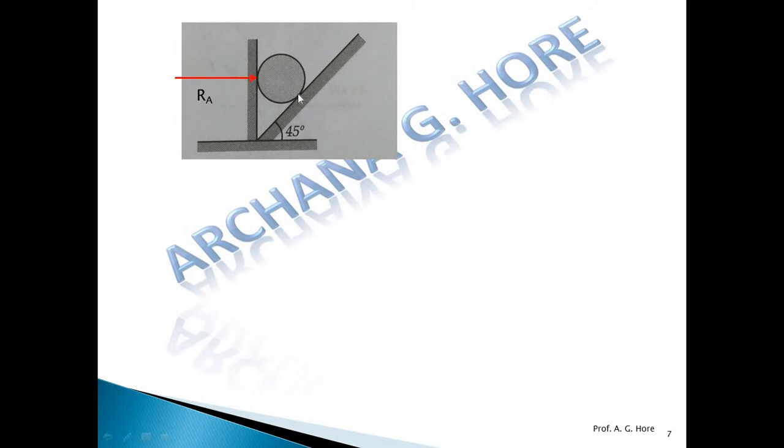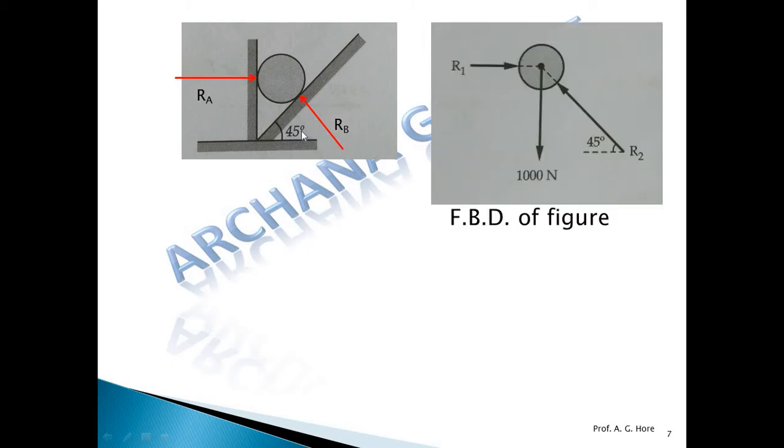Similarly, suppose this point is B, this is the inclined surface, reaction is perpendicular to this surface, like this is the 90-degree angle perpendicular to this surface, but this reaction is inclined and having some angle with horizontal. So this is the 90-degree, this is 45-degree, and we subtract 180 minus the addition of these two angles, we get the resultant reaction at B with horizontal. So we can get that 45 angle.